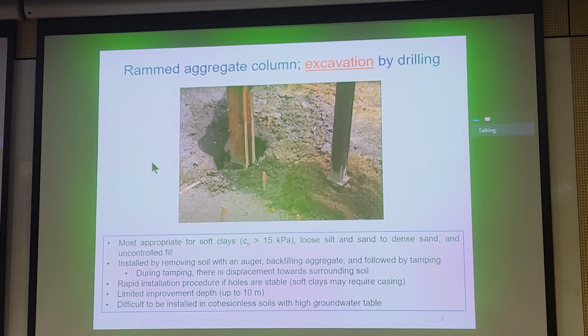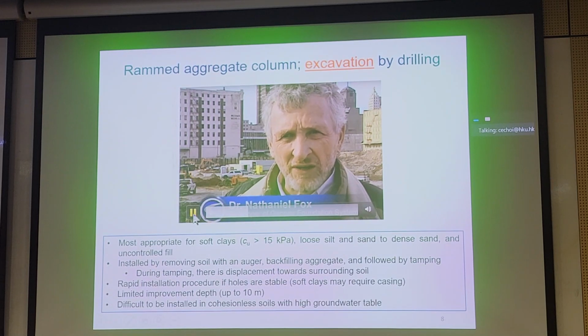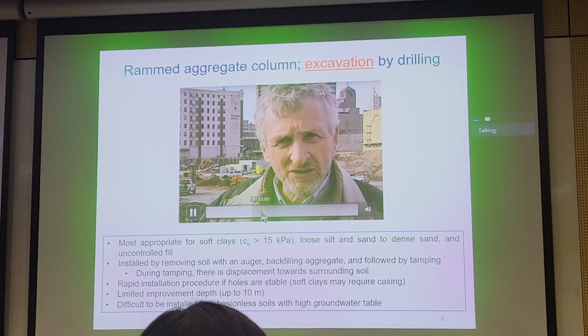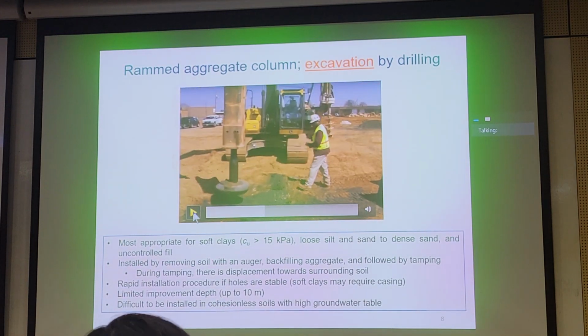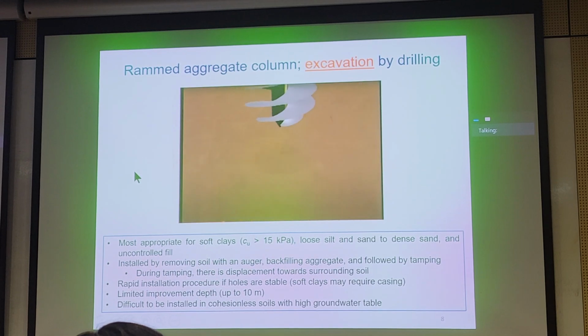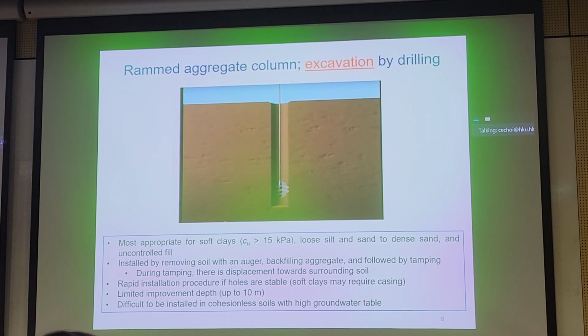So what we do here is we excavate a hole, we pour in gravel, and then we dynamically ram it, and we keep on doing this till we get to the column top. The construction process utilizes pre-augering and impact ramming energy to construct the rammed aggregate pier elements. The augering is the excavation part, removing soil vertically from the ground. First, a cavity is drilled according to design specifications, usually 7 to 30 feet.